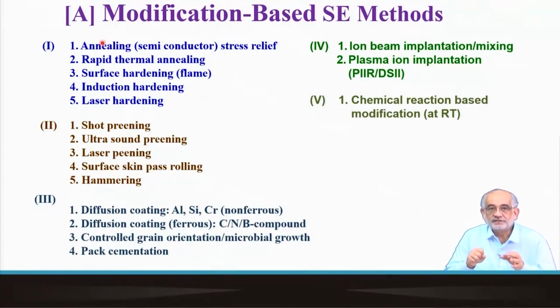So I do a stress relief in a process which is thermally activated, called annealing. I can do that annealing isothermally, or I can do it by rapid thermal annealing, which is basically through a flash of light or a flash of a particular temperature profile. So it's not isothermal, it basically is a profile like this.